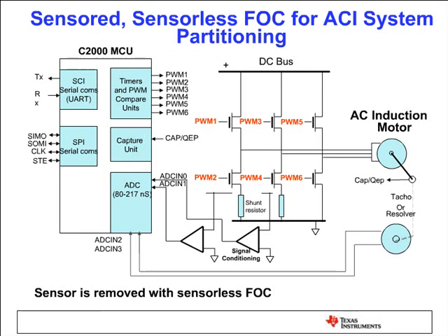Commonly QEP, incremental encoder or tachometers are used for induction motors. Since we don't need very precise position information for induction motor, people prefer cheap tachometers, which are fine, because we don't need to know the precise position, but we need to know the speed. So 10 pulse per revolution type of encoders or tachometers are good enough for induction motors.